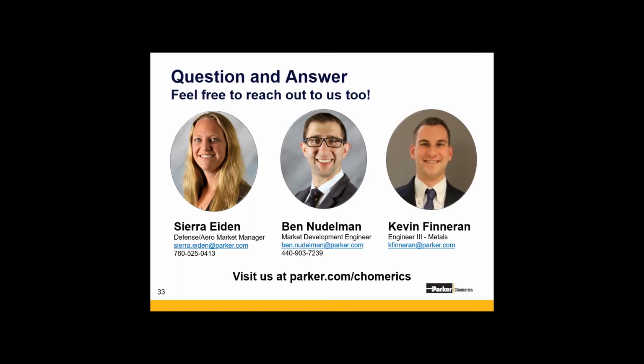Okay. Another one from Sanjeev: does nickel plating help shielding effectiveness? So I'll say yes, it would, but Kevin, do you have any information on nickel plating at low frequencies? So low frequencies, dealing with, I think you mentioned earlier, the H field, that's typically 200 kilohertz and below.